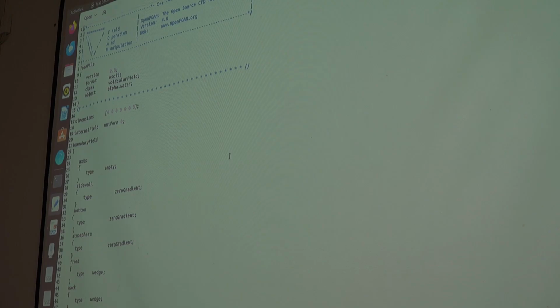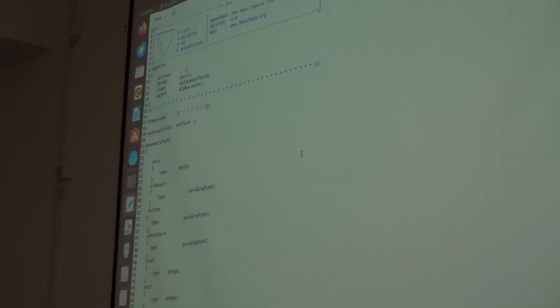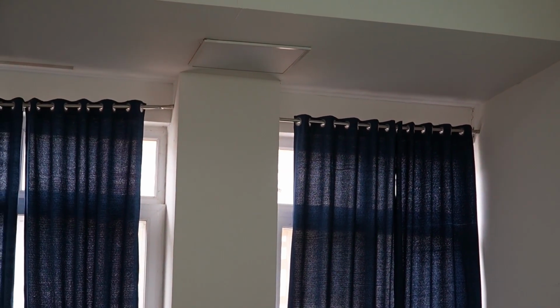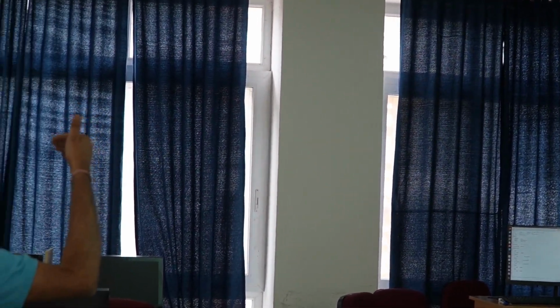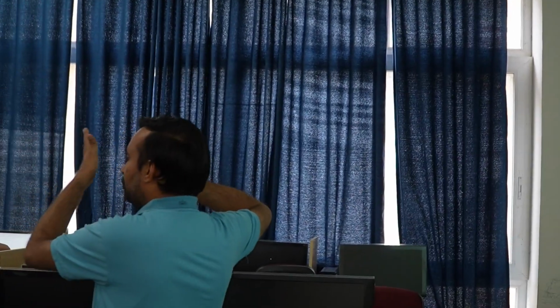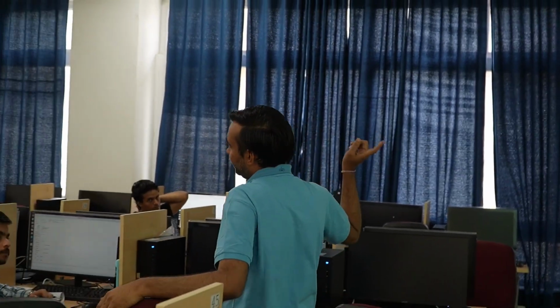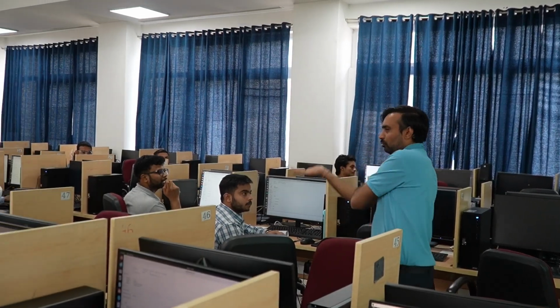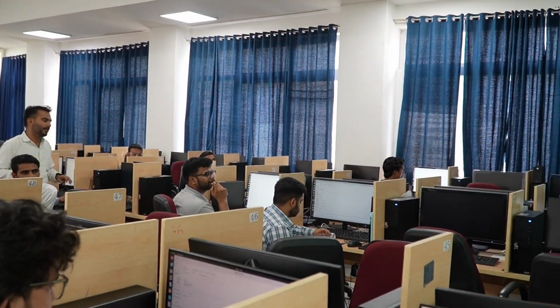And if you recall, I told you, for doing a 2D simulation, the direction along which we do not want to do computations, we specify type as empty. But in an axisymmetric simulation, along the wedge, if I do not want to do computation, I specify type as wedge. Okay, is this point clear? So for axisymmetric we specify type wedge for the faces which are along the angular direction. All are clear with this point?